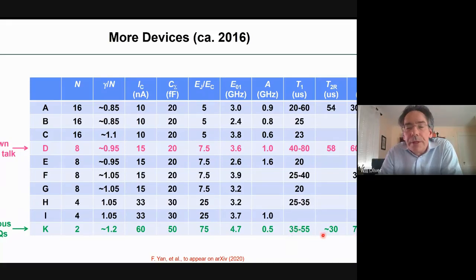And the reason that they were better, I think, was consistent with this engineering framework that we were thinking about. You can see an even higher anharmonicity here, 1.6 gigahertz on a 2.6 gigahertz qubit, but some of the T1s were not as high as we expected, and so that is something that we wanted to study further. And again, I think we will be picking this up again.